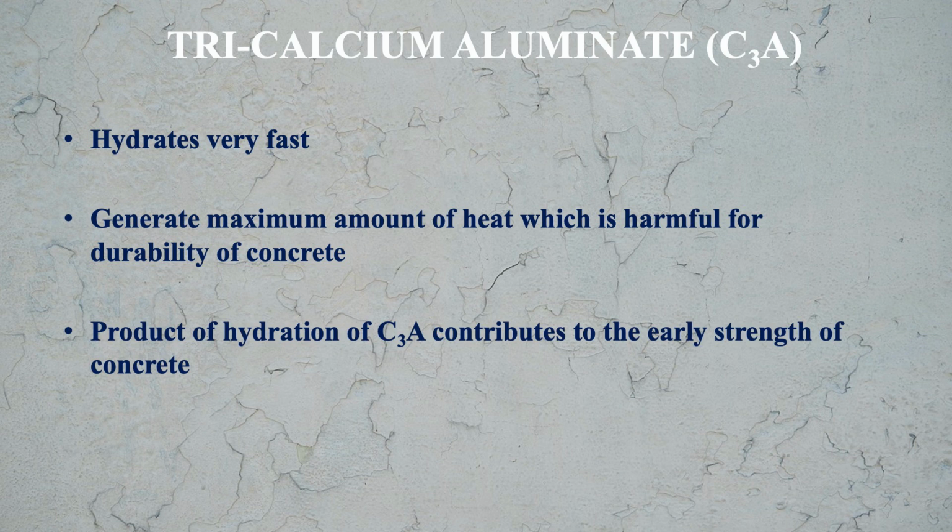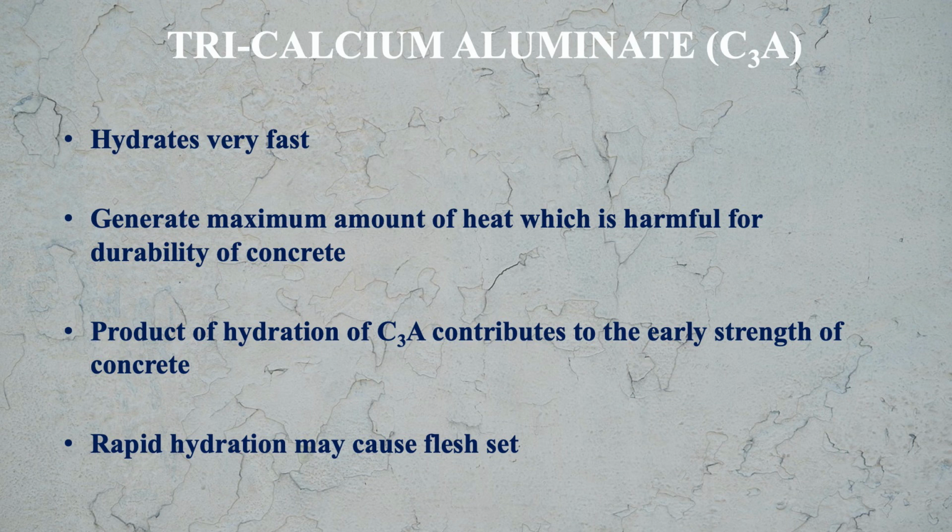The product of hydration of tricalcium aluminate contributes to the early strength of concrete. Rapid hydration may cause flash set. This is the problem. Because of this rapid hydration of this compound, cement may set instantly, which we call flash set.